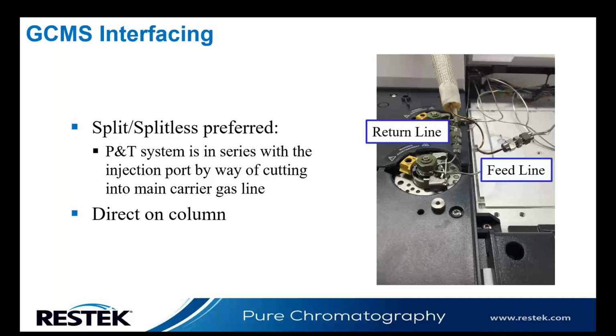Now, what are we looking for when we see a cold spot? You're going to see a loss in naphthalene response. So the naphthalene is generally the first compound that's going to condense on there. And if it condenses for too long, you'll start to see bleed that's associated with that as it's slowly desorbing off of that site there. So those are some things to look for, but it's an easy way to plumb that in to your system, and it works very well.